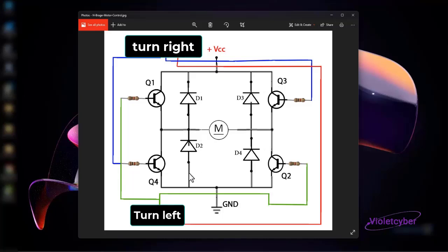Now let's get to the explanation. If you pay attention, for each of these switches, a connection has been made from the positive side of the circuit, one to this connection, and one to this connection. Now, why is this power connected to these components? Because when we press this switch, it must send a signal to the base of its corresponding transistor and activate that transistor. You know that when a transistor's base receives a signal, it becomes active, and then it switches and acts like a switch, right? So we need to give them a signal, which we do using the base VCC voltage, which we have created for each of the switches.